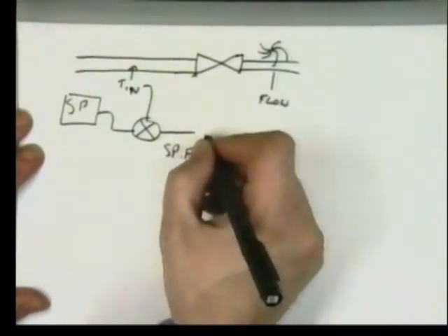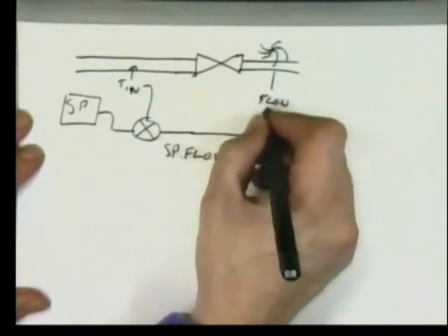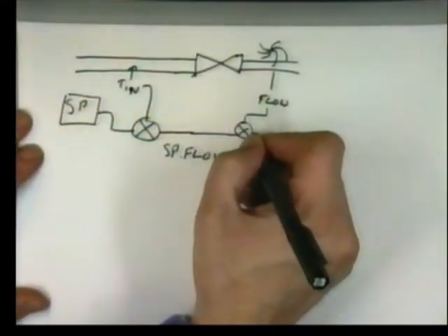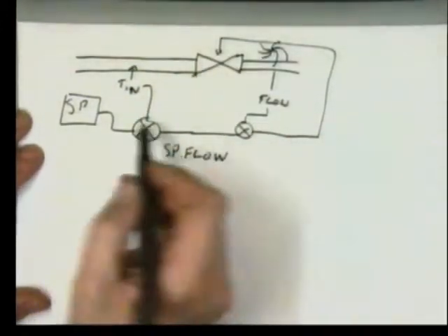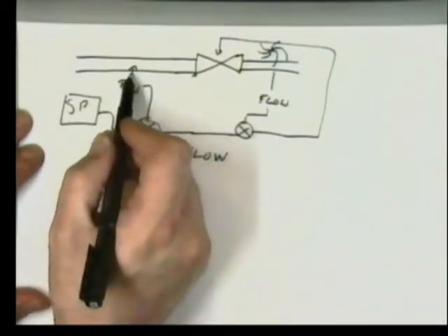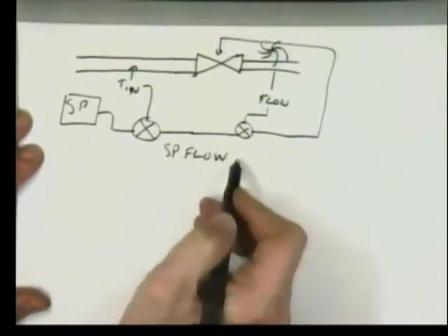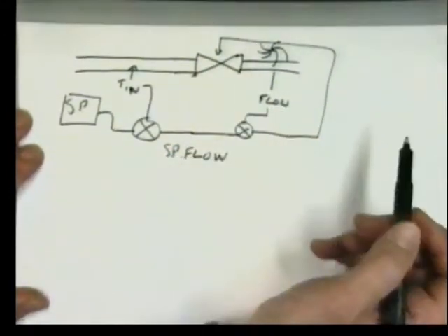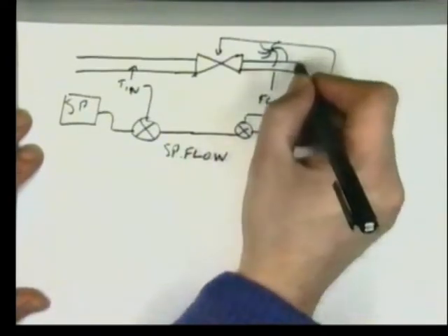And what we did is we used that in a feedback control system: we fed back the flow rate that we measured into a feedback controller, and that is what we used to control the valve. So we had feed-forward control based on measuring the input temperature and the set point to give us a prediction of the flow rate we required, and we used feedback control to control the position of the valve based on the actual reading we had from the turbine meter.